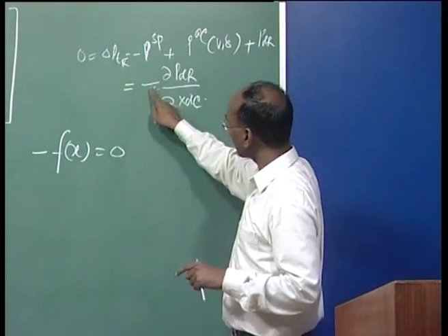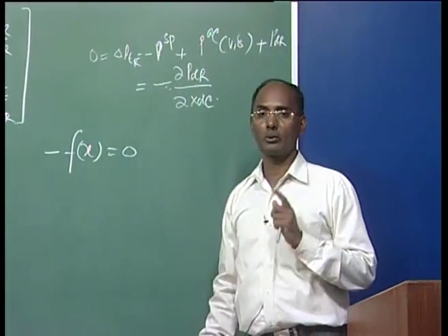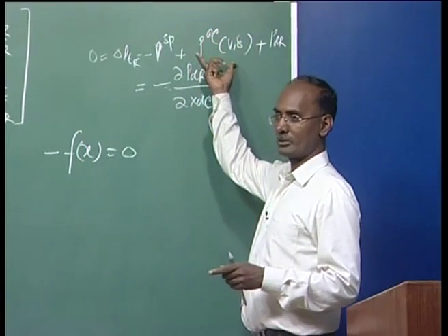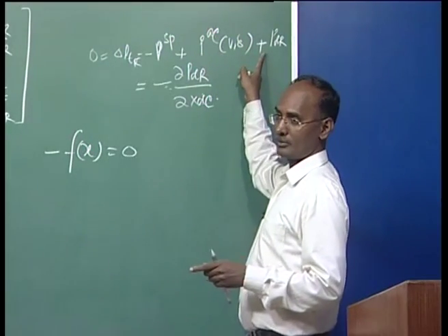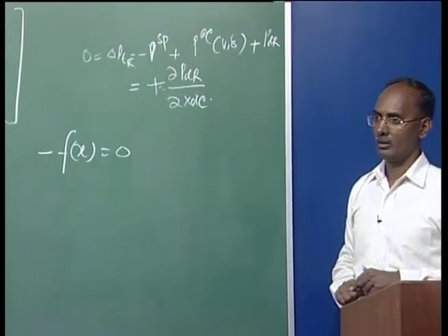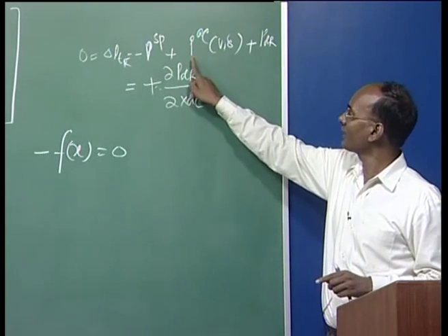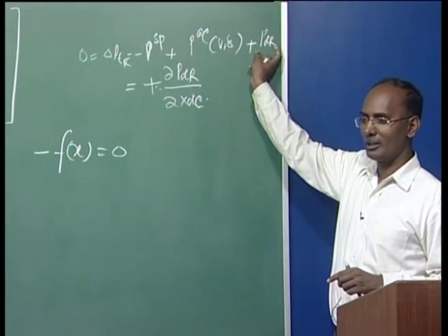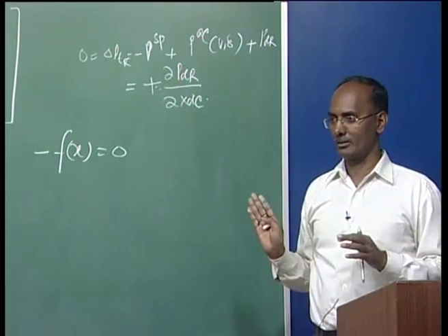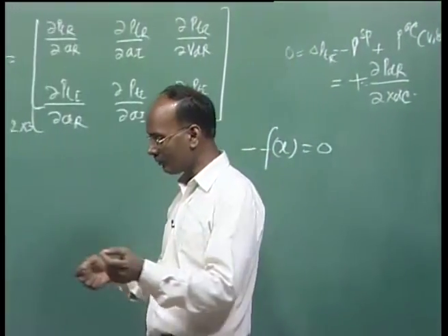Again, whether the sign is plus or minus will be decided by how you are defining H, N and J, L. So normally we do take these as positive Jacobian elements. That is why it is additive. Okay, so here we are also taking the positive. Mind it, this is for the rectifier, so here this and this are added together. If you are going for the inverter, this will become negative, because it is coming just like a generator. So the only difference is in the real power. However, the reactive power is always taken as load and it will be coming out from the bus.